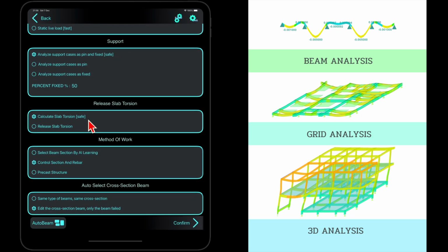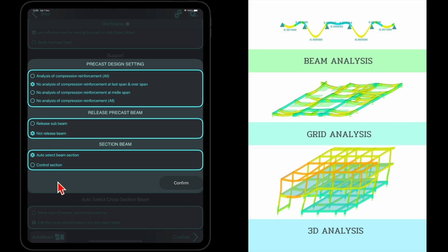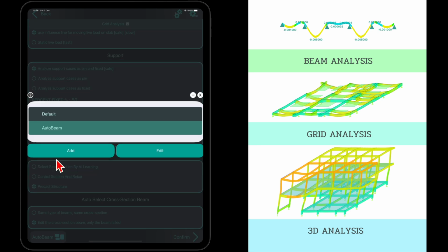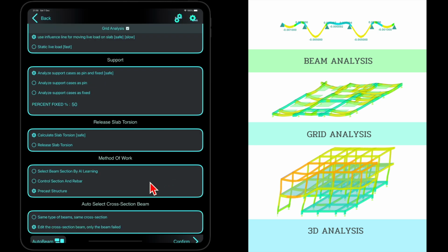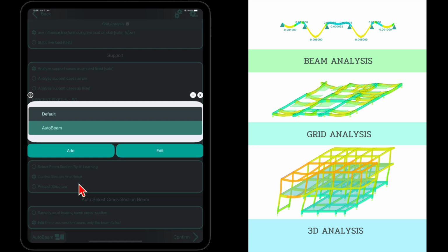3. Enhanced design options for beam sections and reinforcement placement. This option builds on the first two and allows you to prevent beam designs where reinforcement is subjected to compressive forces. You can define the location where this is applied, mid-span, near the supports, or both. If compression reinforcement is required, the program will switch to a larger section to ensure the concrete resists all compressive forces.